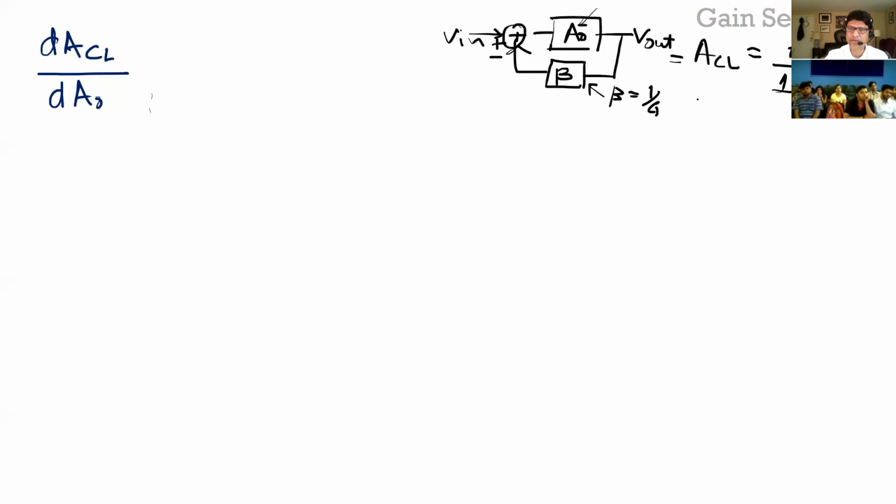And it's very easy to get an attenuator. You just take a resistor divider, for example. That's your attenuator right there, right? So some V in here and that V out here, and you get an attenuator. That's very easy to get and very accurate. And the ratio of resistor variation, even in a chip, you can get to within 0.1%. That's very accurate. And that's why we can use this technique here, right?